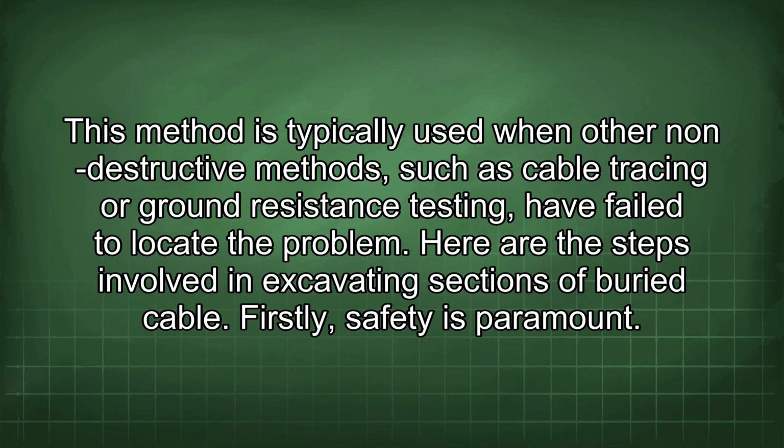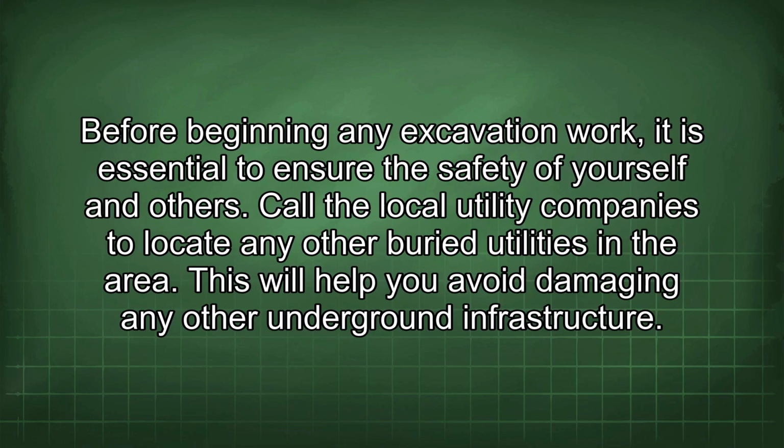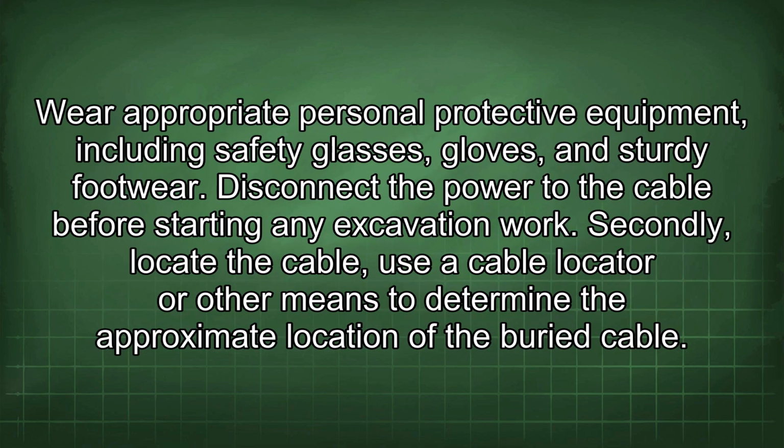Firstly, safety is paramount. Before beginning any excavation work, it is essential to ensure the safety of yourself and others. Call the local utility companies to locate any other buried utilities in the area. This will help you avoid damaging any other underground infrastructure. Wear appropriate personal protective equipment, including safety glasses, gloves, and sturdy footwear. Disconnect the power to the cable before starting any excavation work.